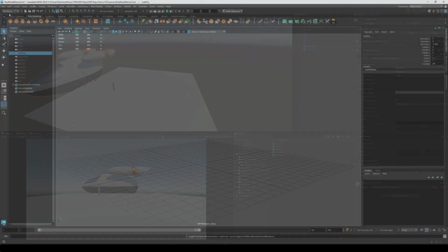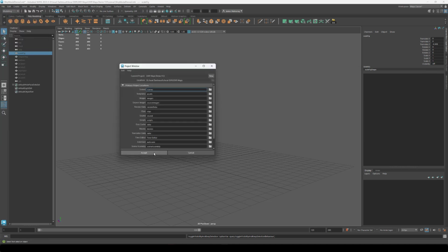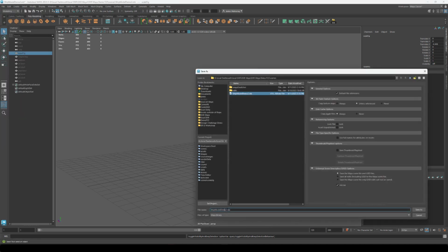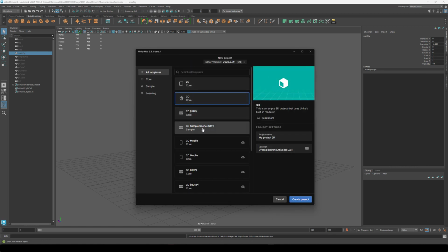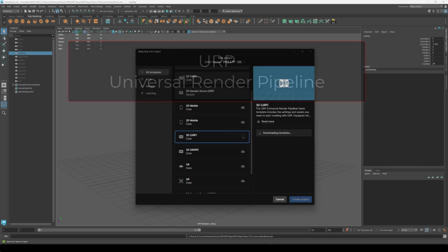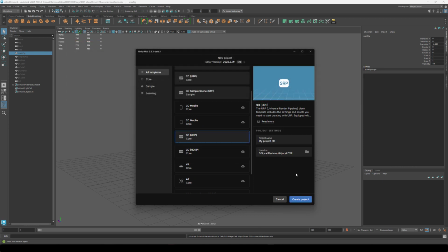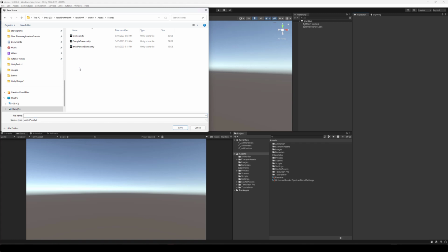Let's start with process. Open up Maya and create a project and set Maya to that project as you've done in CS22. Create a new Universal Render Pipeline Unity project as well. We'll be using this render pipeline in the class. The workflow from Maya to Unity is pretty sweet actually. The only really tricky thing is that Unity is a real-time renderer and so requires a slightly different approach to modeling. It's generally less forgiving. Beyond that, it's a bit tricky to make sure you're working to scale.